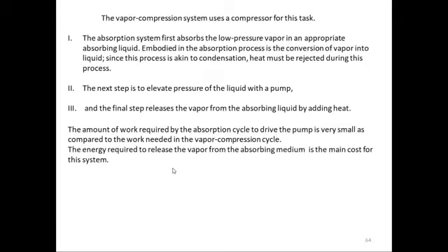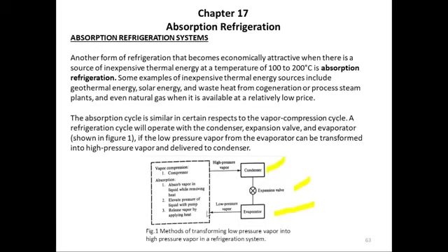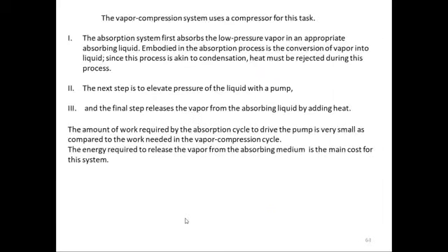So you have an absorber, a generator, and a pump. That is what replaces your compressor. Absorber, pump, and release vapor. So that is the generator, releasing vapor by applying heat. I'll show you the diagram, the sketch of the system, then you'll see it there.